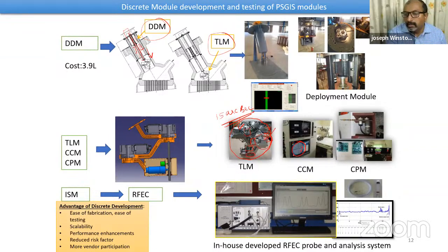These developments are also electronically controlled through the distributed control system, with the motion controller interfaced with the HMI screen through a field bus, Modbus. Based on the inputs taken from the HMI, the motors are run to position the arm. Then the pusher modules were developed and tested discretely: the cable pusher module and cable dispenser module were tested discretely and then pushed into the integration of the overall system.